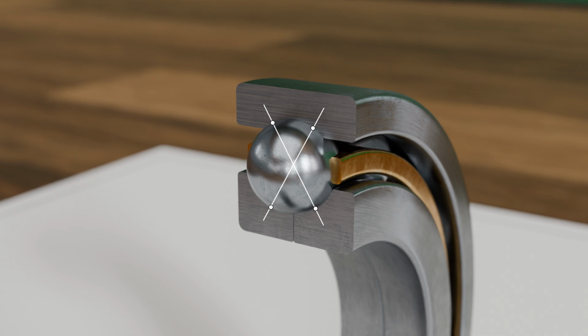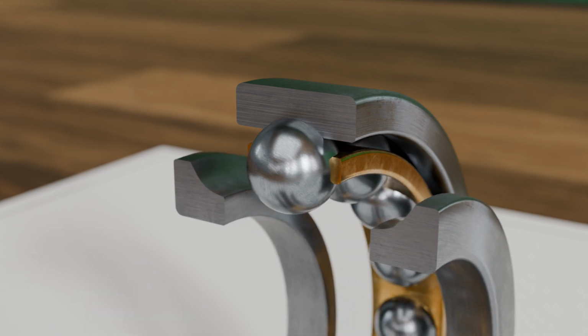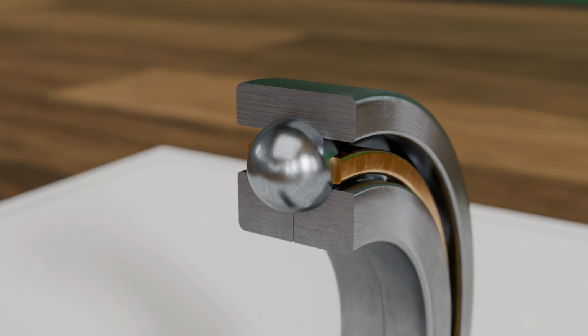A design advantage of this bearing is that the outer ring together with the ball cage can be mounted separately from the split inner ring. Since the individual bearing components are not firmly connected, this type of bearing is also referred to as a non-self-retaining bearing. This particularly facilitates assembly in difficult installation conditions or complex housing designs. Since four-point bearings are primarily designed to accommodate axial forces, higher radial loads must be absorbed by additional bearings, for example, through combination with a cylindrical roller bearing, which we will discuss in more detail later.